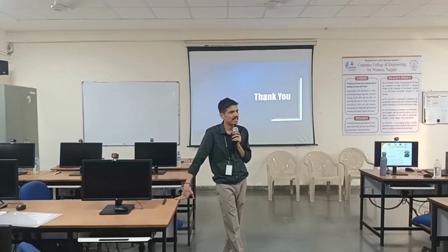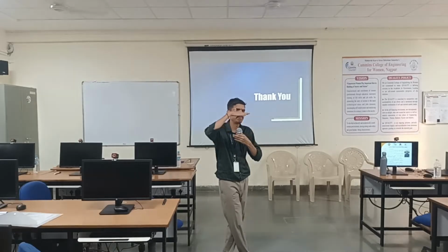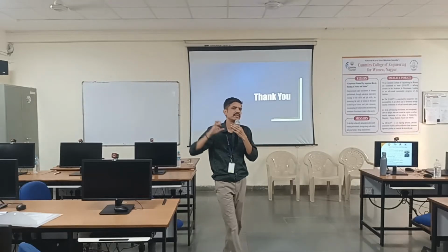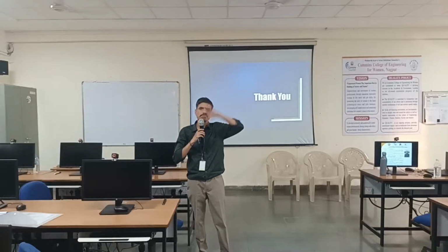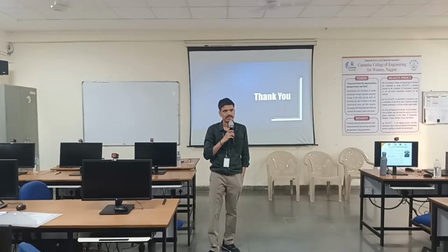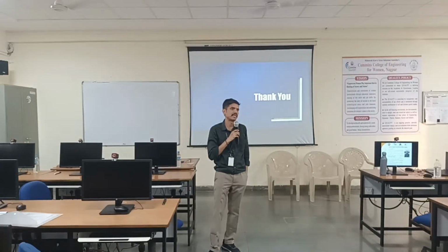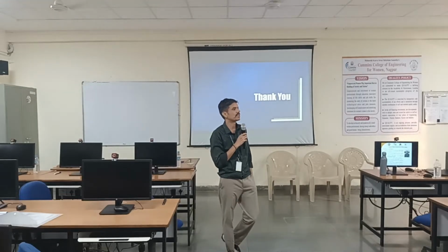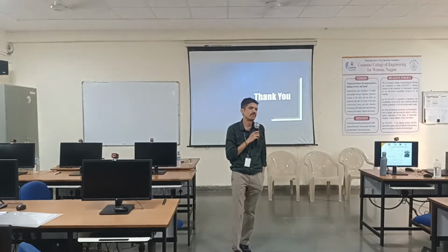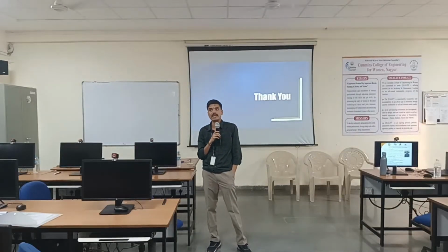Then 2018 started. I was looking for a Doherty power amplifier. This was general. This amplifier is called a balanced power amplifier. Two amplifiers are placed in parallel, with a 3 dB coupler at the input and a 3 dB coupler at the output, with bond wires etc. That was done. But that is a balanced amplifier, and I was looking for a Doherty power amplifier. In the Doherty, the efficiency I got was 45% in the KU band. I was looking for at least 50-55%, so that I could have some novel PhD work.